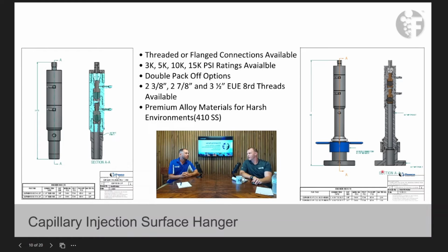And then what do you do once it's cut? From that point, you fish. Typically your internal unit should have fishing tools. If they don't, you need to get braided line to come out and fish your string out of the hole. Okay, so you can use that internal unit that we showed earlier to pull it out, because that cap tubing is just sitting down on the inside of the tubing, right? Yeah, typically the head on an internal unit can pull roughly 8 to 10,000 pounds.